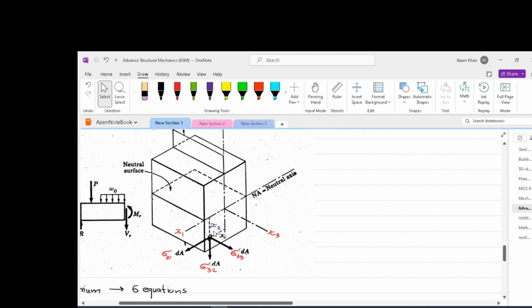If we add the product of area times these two lever arms for all the four elements, we will get 0. So an element which is at a distance x2, x1 from the coordinate axes in all the four quadrants is summed up by keeping the absolute distances x1, x2 the same.